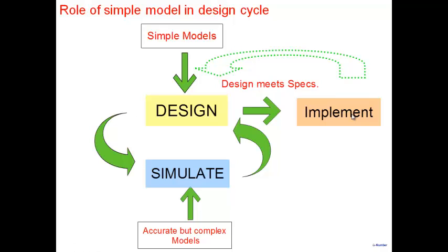Okay, so we can't use the BSIM3 model for initial design or for initial analysis. So we are stuck with the level 1 model, and you have to keep in mind that when you simulate the design you did with the level 1 model using the BSIM3 model, there will be a lot of discrepancies. But using the simple model, we would understand the circuit. Let's say you want a gain of 500 and you're getting 200, but through the simple model we understand the schematic. We know how to increase the gain if we increase RD or increase gm or decrease the current and all that. So using that, you can fine tune your circuit.